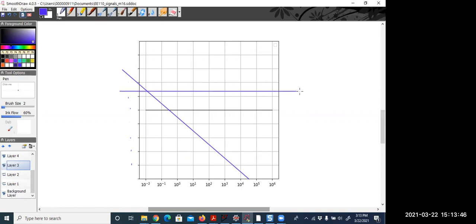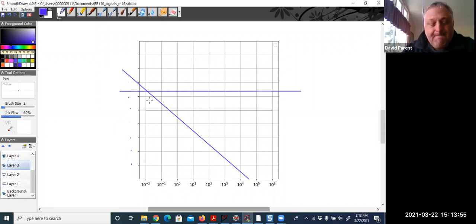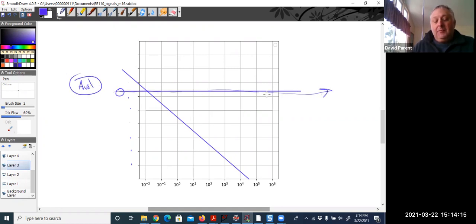Professor, can you explain again how you get this Bode plot? I'll go over it briefly, but this was from last time. This right here is from the data sheet, and it's the DC value, and you just draw a straight line asymptotically here. And then that point is 0 dB, and it assumes a first order integrator type thing.